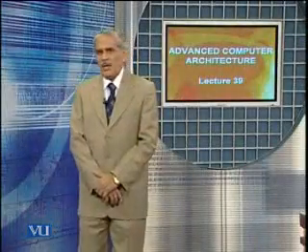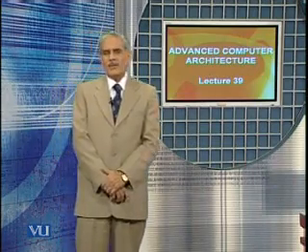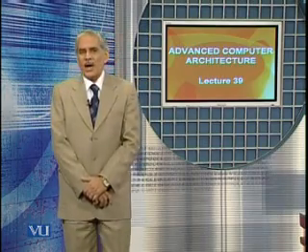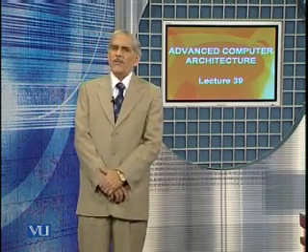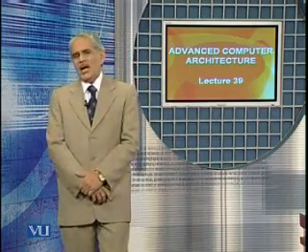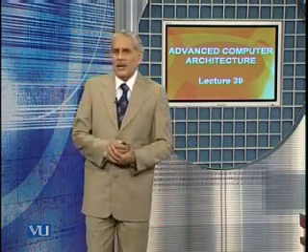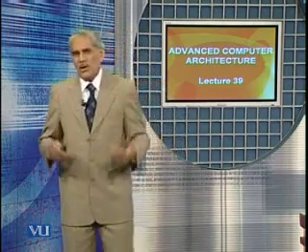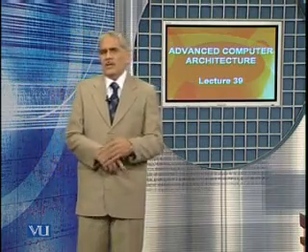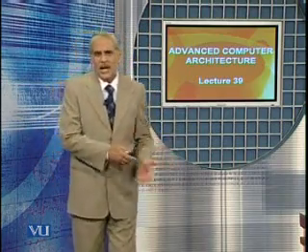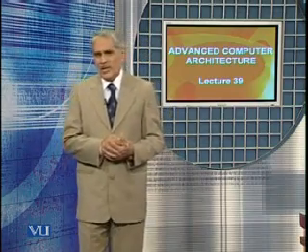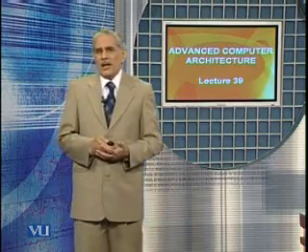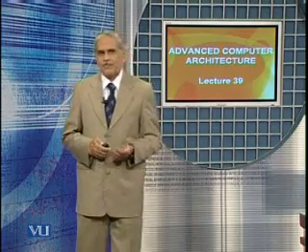Then the fourth step is that it uses the bus, and the fifth step is it signals the bus is no longer required. When it finishes, it signals that the bus is no longer required, and it does this by asserting the release line. So by following these 5 steps, the transaction is completed, the bus is handed over to the highest priority request, and then when it finishes, it releases the bus for the service of the next request.